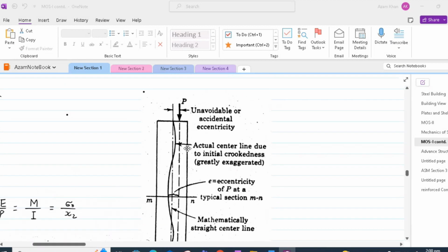Hence, there are two extremes. One extreme is that a short column carries principally a direct compressive stress, and the other is a long column, which is subjected primarily to flexure stresses. As the length of the column increases, the importance of direct compressive stress decreases, and that of the flexure stress increases. Unfortunately, in the intermediate column range it is not possible to determine the rate of change in these stresses or the proportion of each stress that constitutes the resultant stress.